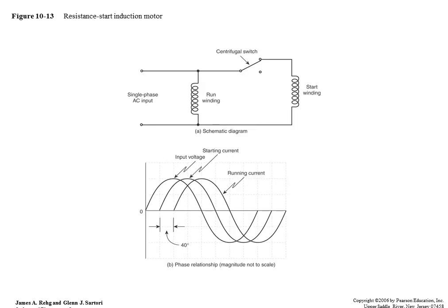Okay, now we have 3 phases to worry about. I guess we don't. This is a single phase motor, and I've got a starting winding thrown in, to keep the currents down. And then when I get fast enough, a centrifugal switch happens so that I turn off the starting winding. And there's a difference in phase between the starting winding and the running winding. And that difference in phase is what's going to keep me from going over currents and burning the thing up.